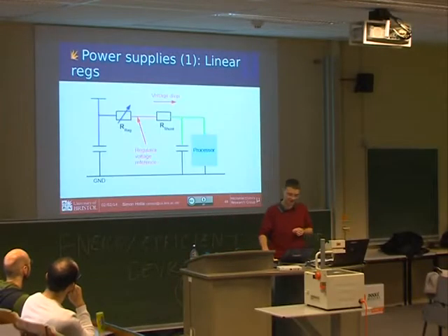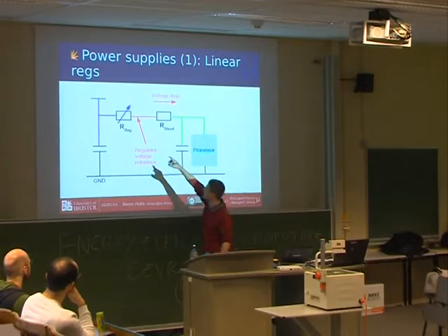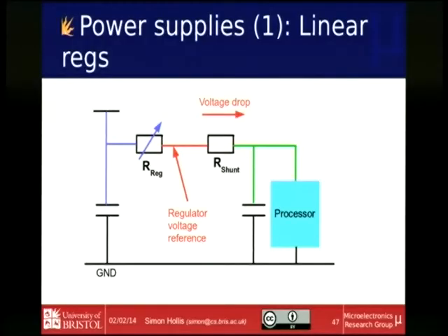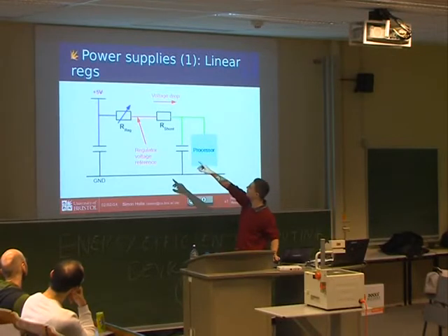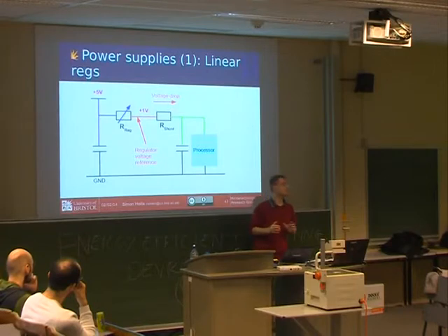And it's really a big transistor. So there's a representation, it's a transistor, it changes its value depending on the input voltage you put in there. It's a regulator, and you get out whatever you bought on the package. The package normally specifies 5 volt output, 1 volt output, whatever you get, what you get out. So you get a voltage out here, 5 volts goes in, 1 volt might come out, and then you add in the shunt resistor for your measurement.